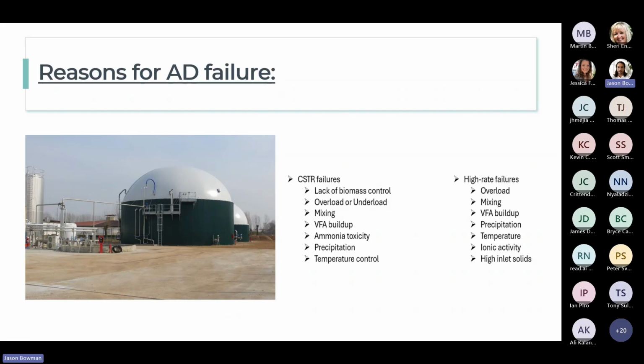Option 5, in these situations where ammonia toxicity becomes an issue, recuperative thickening can actually be used in combination with dilution to help with the toxicity element. So in those situations, the ammonia concentration can be diluted by adding some clean water, while the DAF process really focuses on capturing and maximizing bacterial concentration. So while we're diluting water on the one hand, we're still maximizing our bacterial or biota concentration on the other hand, so that we can recirculate the bugs in a more effective manner and really give them a fighting chance to keep up with what's going on inside of the digester.